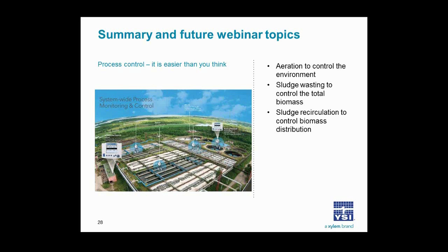Of course, total phosphate, or TP, is usually the compliance parameter, but that parameter is really a function of how well your separation device is working. So, for example, your final clarifier or your filter. And for controlling those, you would want to use sludge blanket level and TSS to make sure that that particulate phosphorus is captured and doesn't escape into the effluent. Well, I guess those are really the main measurements that are applicable to P removal.